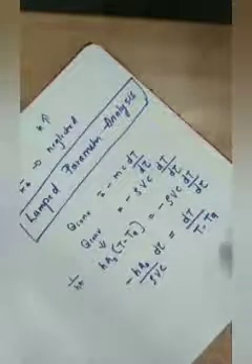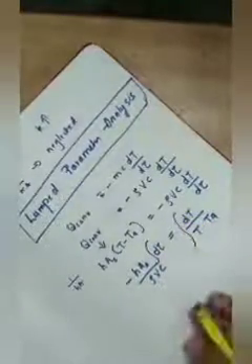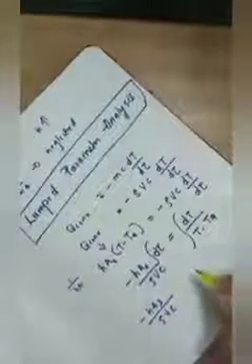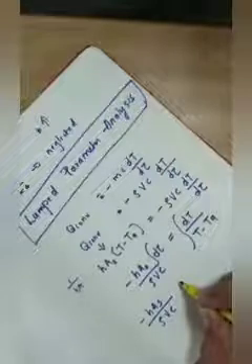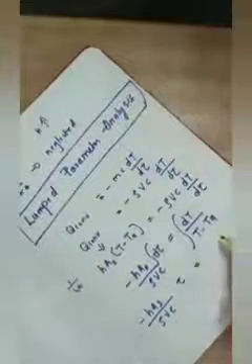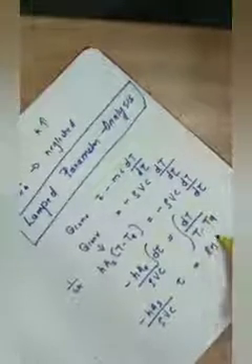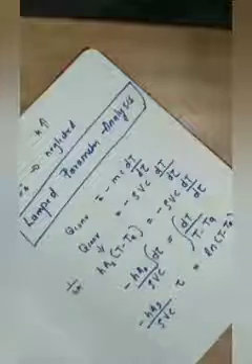Now the next step is very simple. We can integrate it. This is a variable separable form, so we can integrate d tau on one side, and on the other side we get minus h As by rho V c times tau, which equals the integral of dT by T minus Ta, which is log of T minus Ta. I am adding a constant C1 here.